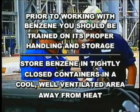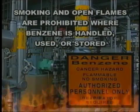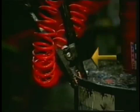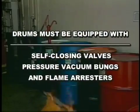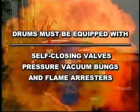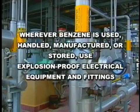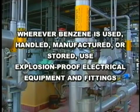Prior to working with benzene, you should be trained on its proper handling and storage. Store benzene in tightly closed containers in a cool, well-ventilated area away from heat. Sources of ignition, such as smoking and open flames, are prohibited where benzene is handled, used, or stored. Metal containers involved in the transfer of benzene should be grounded and bonded. Drums must be equipped with self-closing valves, pressure vacuum bungs, and flame arresters. Wherever benzene is used, handled, manufactured, or stored, use explosion-proof electrical equipment and fittings.